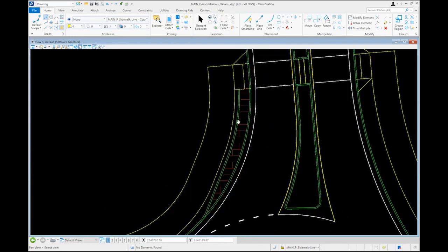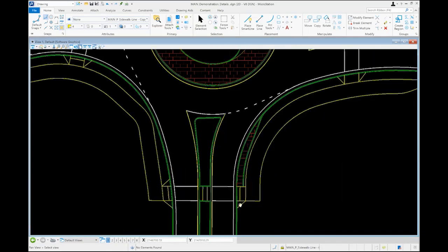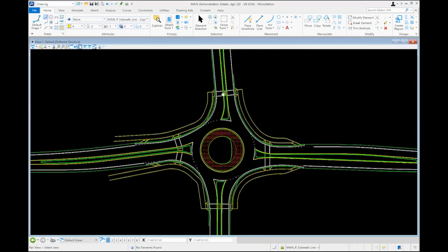Between the back of the truck blister and the sidewalk, we want to make sure that we're maintaining at least 2 feet of separation along those areas on both sides. So both of these are maintaining at least that 2-foot separation, again, to delineate the ped space from that vehicle space. And then these crosswalks have also been set back a little bit further. So these are 2 car lengths back on these 2 legs instead of 1 car length back.